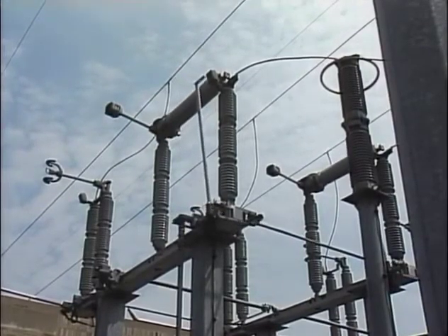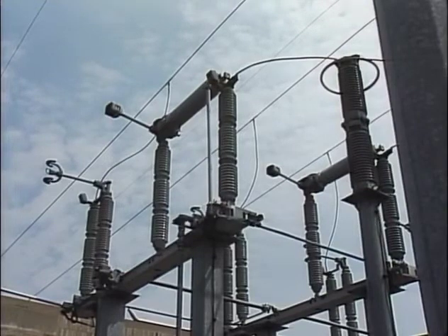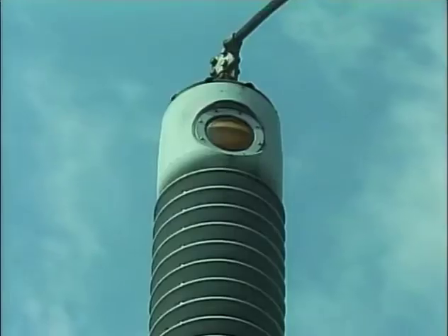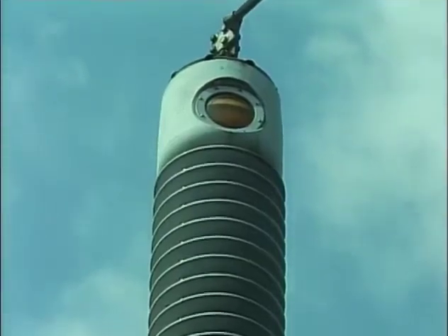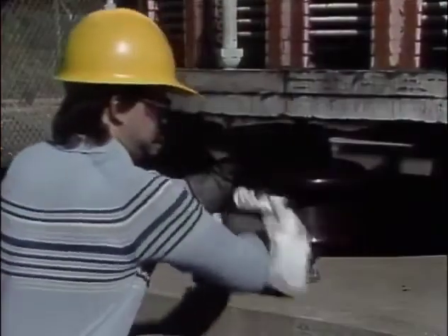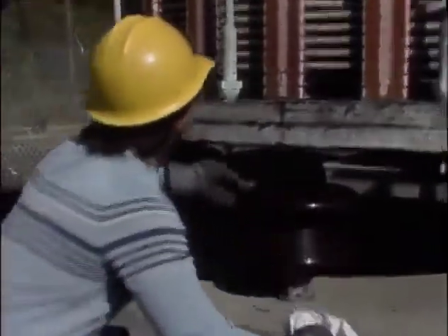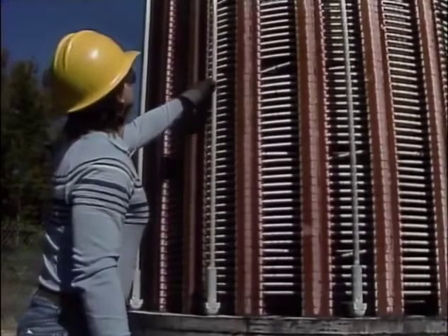With the reactor properly grounded, a couple of very simple maintenance tasks can be performed. One task for an oil-insulated reactor is to clean and inspect the bushings. For an air core reactor, the support insulators are cleaned, and the windings and winding shims can be more closely inspected. Finally, the insulators for the reactors can be tested using a megohmmeter. The test is very similar for both the oil-filled shunt reactor and the air core shunt reactor, so we'll watch how the test is performed on just one of them.